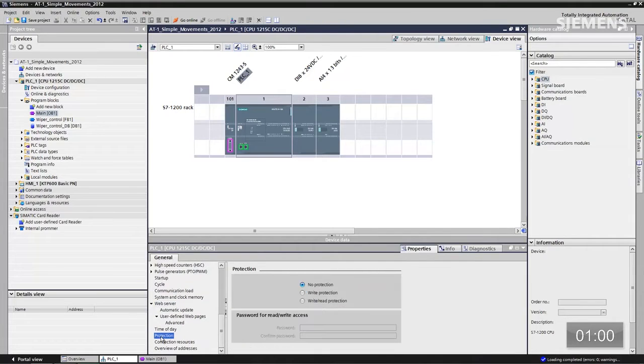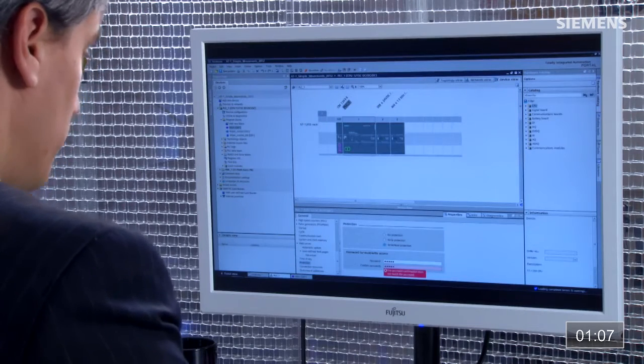That way we have the ability to make it more difficult from a security standpoint of somebody being able to sniff out the connection from the smart device to the control system. Okay, what we want to do now is go down to Protection and click on Read-Write Protection and add a password in of admin once and twice.